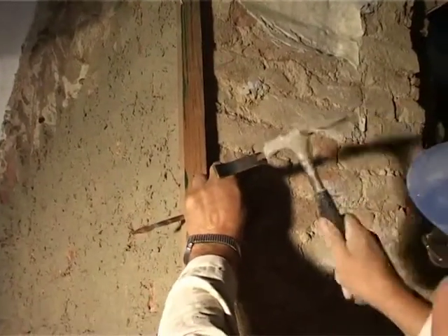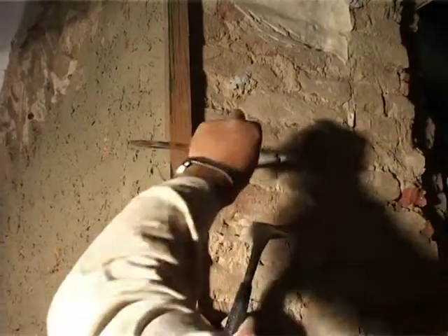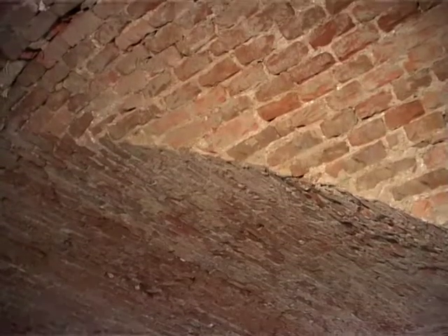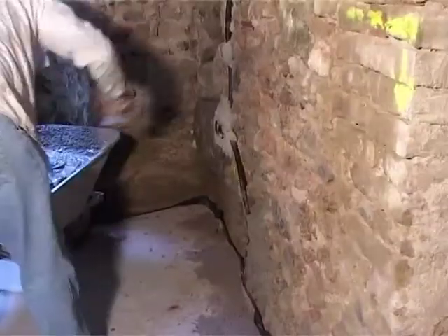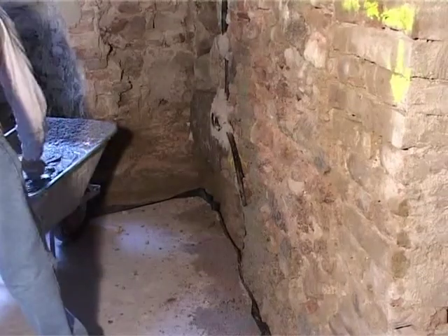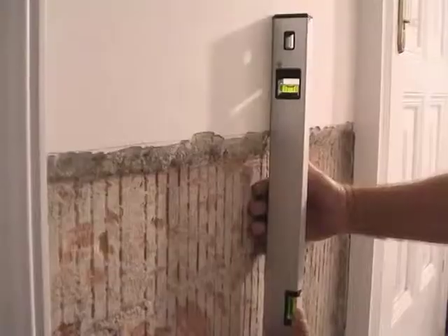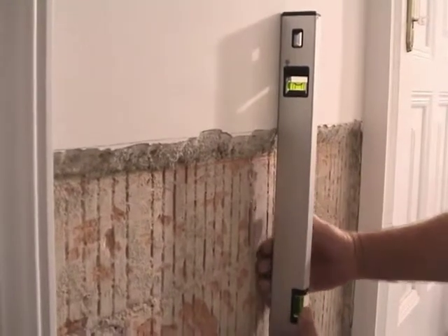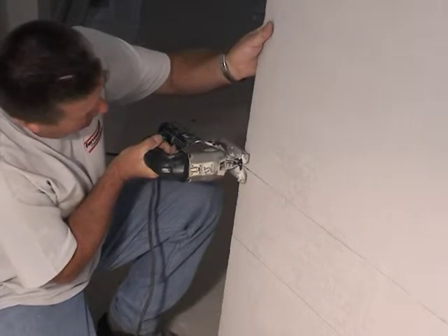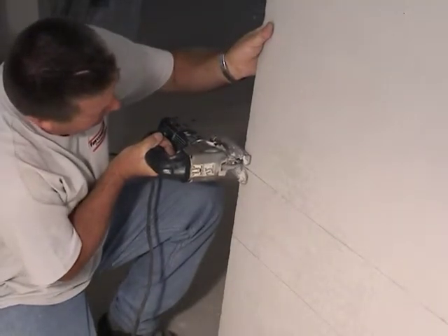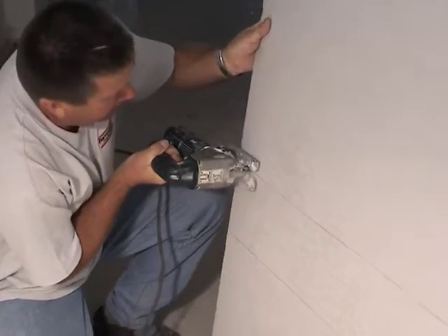If the wall merely needs a new coat of paint, it should be painted after the evaporation phase. According to the ÖNorm, the Austrian standard, and according to our long years of practical experience, the actual plaster renovation should be performed only after the wall has been dried. One thus avoids migration of the salts into the new plaster and consequent undesirable chemical reactions.